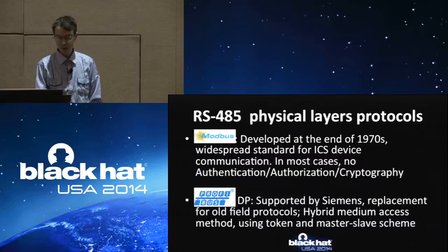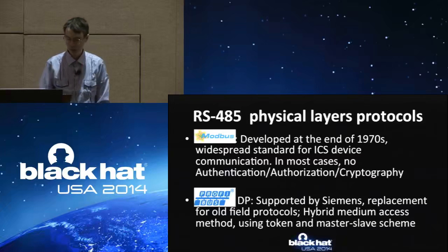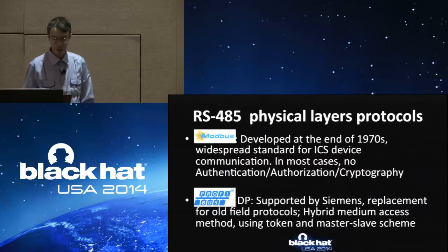Profibus DP is a protocol that was developed as a replacement for all field protocols. It also works over RS-485 and has a hybrid medium access method using a token and a master-slave scheme.